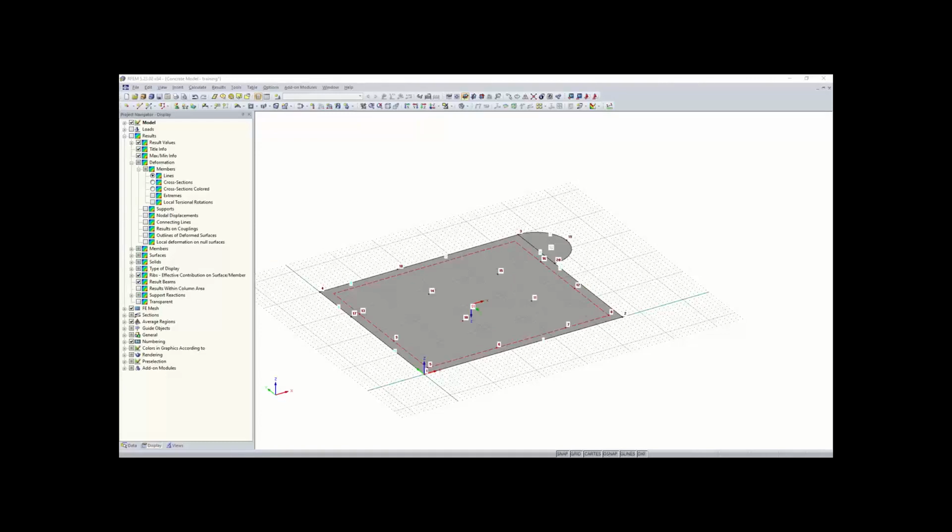And so now, after surface 2 has been created, we can work on our ceiling slab. And this should be pretty easy since our ceiling slab is going to be symmetrical, or basically the same as our floor slab. What we can do is highlight our floor here, and then we're going to move and copy it.